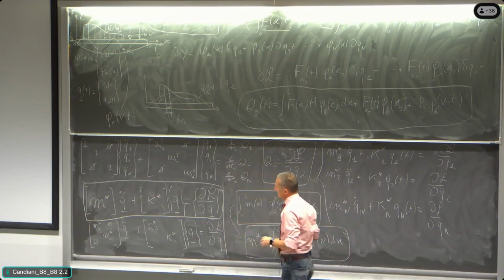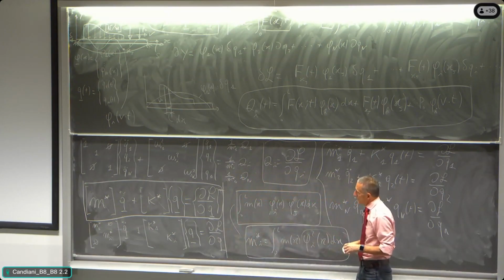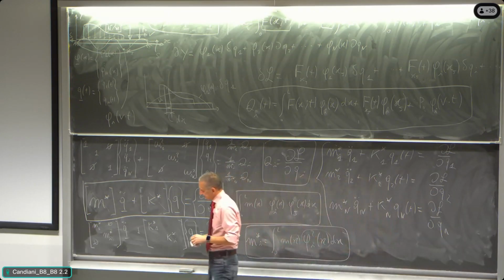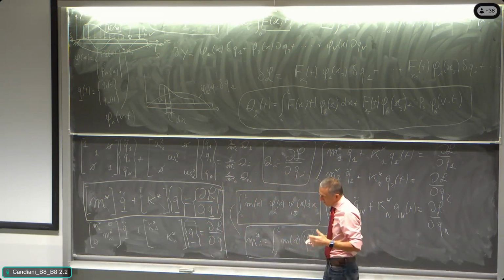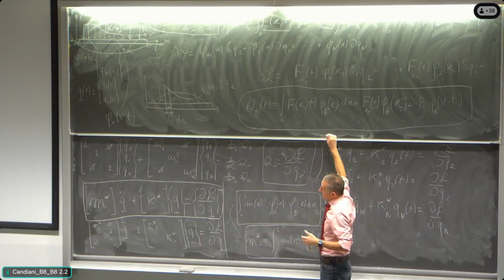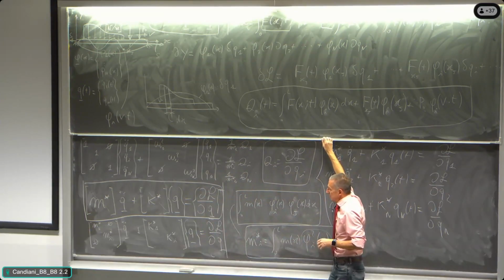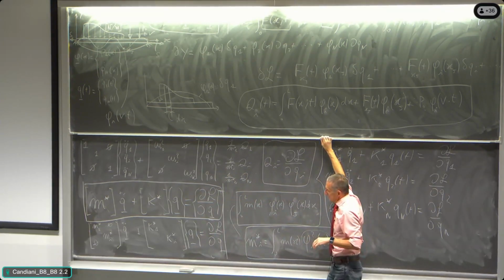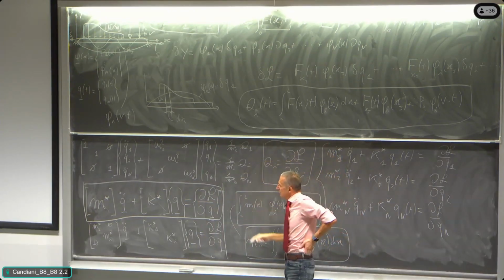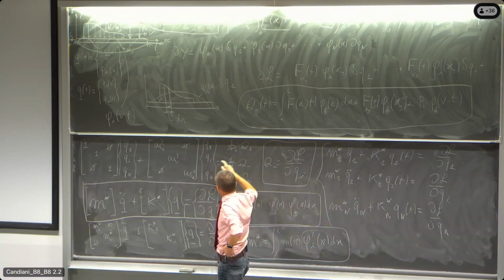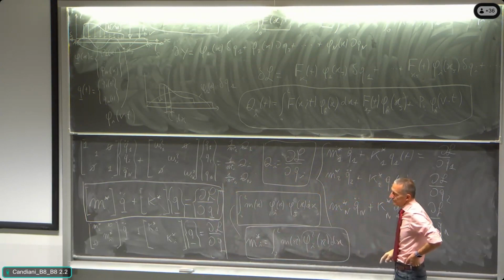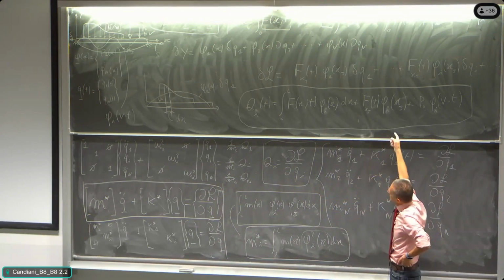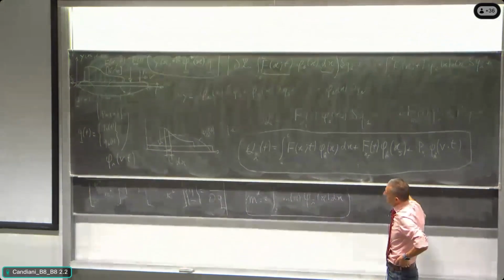And so what we are saying is that in very large generality, it is possible to write, for small displacement, the dynamic problem of the continuum through the principal coordinate hypothesis, through the representation in terms of principal coordinates of the distributed displacement of the structure, with the superposition of n systems, 1 degree of freedom systems, excited by a time domain function that is defined through the Lagrangian component of the external forces, described in the way that we did for those simple cases.